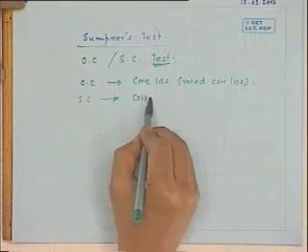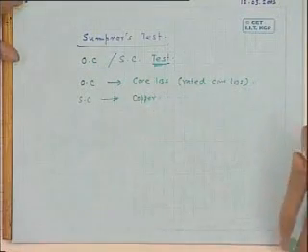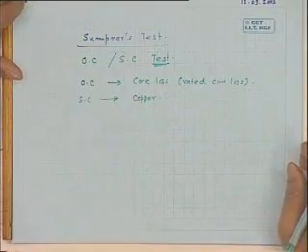But in that case, what loss predominantly takes place? Only the copper loss. Of course, there will be some core loss also, but that is much smaller compared to the copper loss, because you are applying a very small voltage to circulate the rated current. Flux level will be very small, so copper loss will take place.